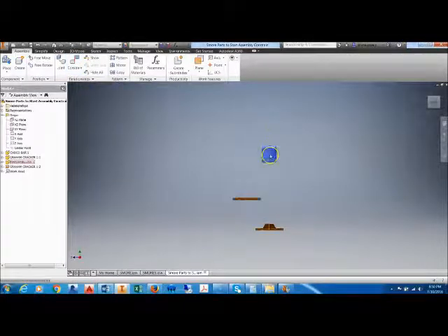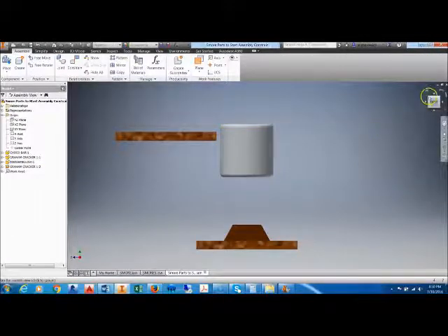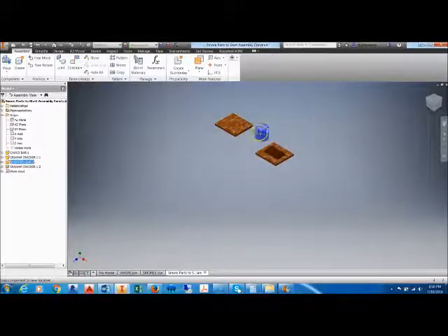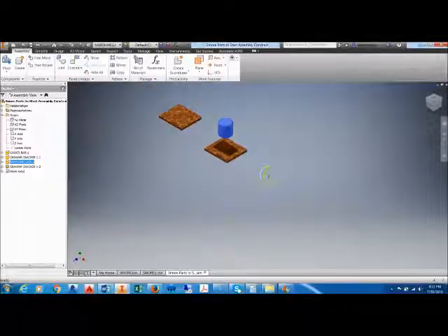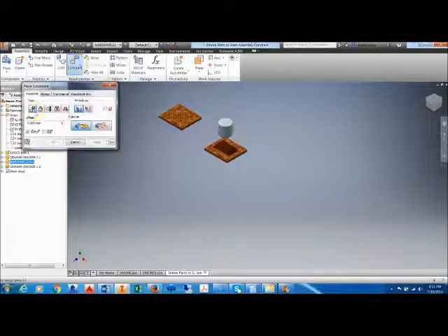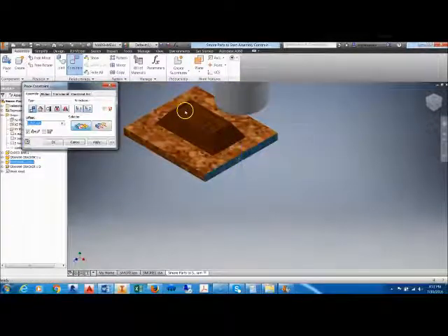I could take and then move this closer, and you can see that this is now located on the center of the assembly. However, what I will still need to do is I will need to be able to locate this from a second edge in order to fix the marshmallow to the center. So I will use that same particular axis constraint, mate to mate, and select that axis to a face, and it will use the same exact number again, where that will be